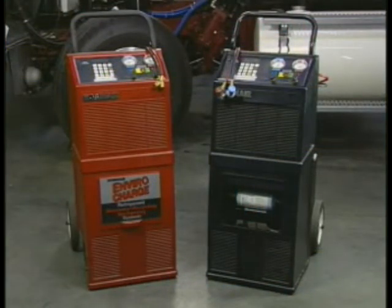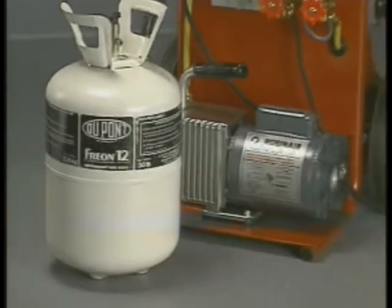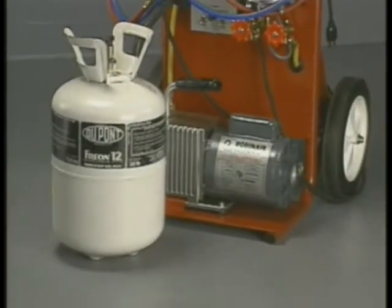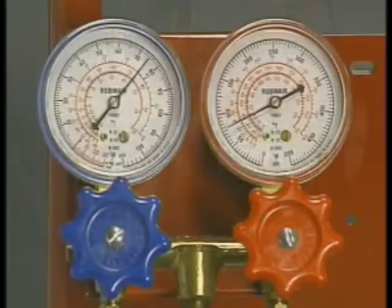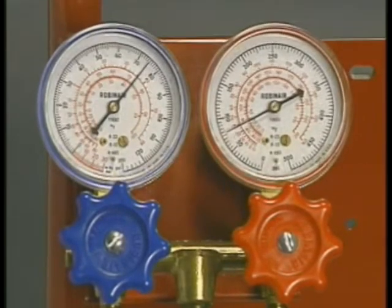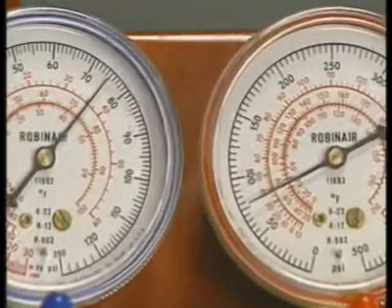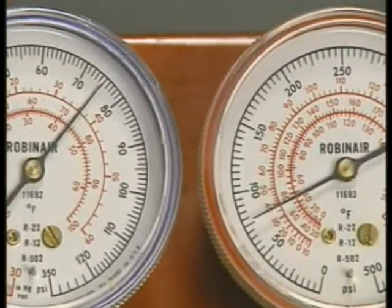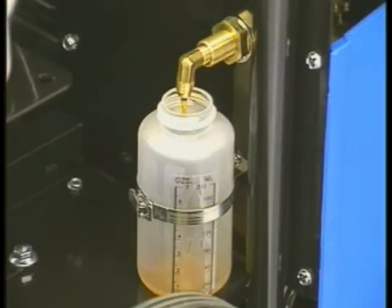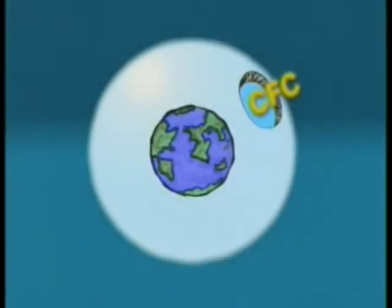There are two common refrigerants used on today's vehicles. The properties of refrigerant R12 made it the refrigerant of choice for automotive systems for the first 50 years. R12 was very good at withstanding high pressures and temperatures without degrading or decomposing. It was considered ideal for automotive applications because it worked at relatively low operating pressures and was very stable. R12 systems used mineral oil, carried in the refrigerant, to lubricate the compressors. Refrigerant R12 is a fluorinated hydrocarbon that was found to be detrimental to the ozone layer of the Earth's atmosphere.